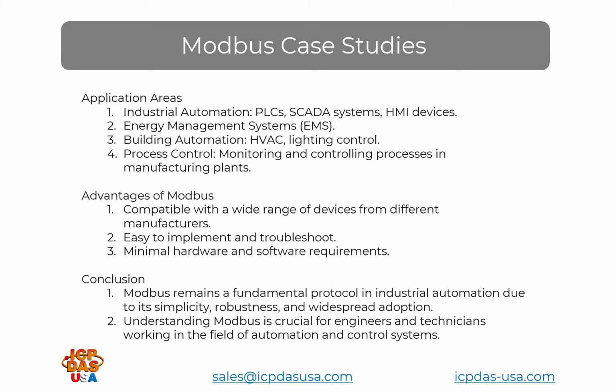As for a third-party data logging device, I guess you could use Indusoft, the free trial, to just graph it, but our Modbus Master utility and Modbus Master tool only show you the real time. It doesn't actually show a historical value. But the Easy Data Logger software can be used for that. But again, it does require at least one of our data acquisition modules to be connected. Otherwise, it'll have comm errors.